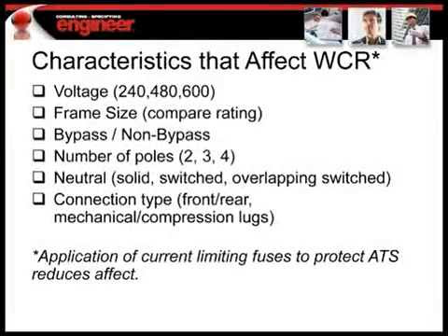This is a summary of the parameters that you need to consider when you're specifying transfer switches. These parameters affect the withstand and close-in ratings of transfer switches. The characteristics include the voltage, the frame size of the transfer switch, and whether the switch is a bypass or non-bypass isolation type switch. How many poles do you need for your switch? Typically a switch is 3 or 4 pole.